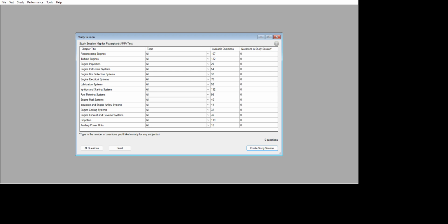Why is 2 not true? The wire gauge should not be placed between the electrodes when moving the ground electrodes on a massive electrode spark plug. If the wire gauge is between the electrodes, pressure will be applied to the center electrode, and the nose core insulator will be strained and possibly cracked.